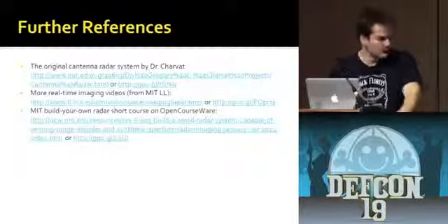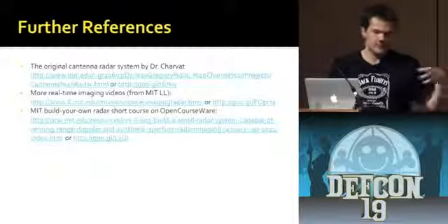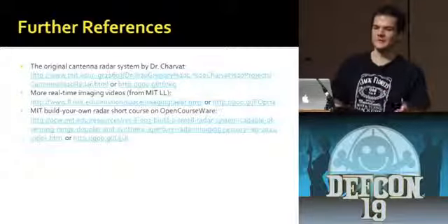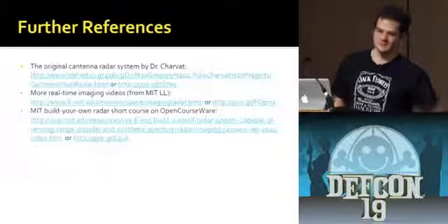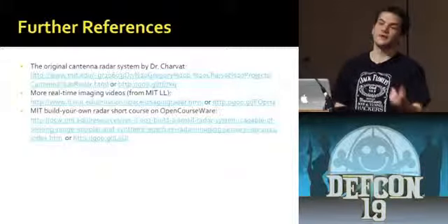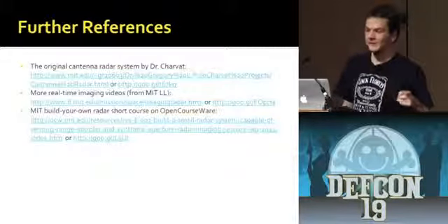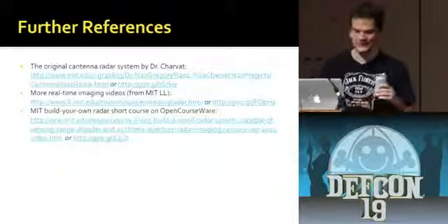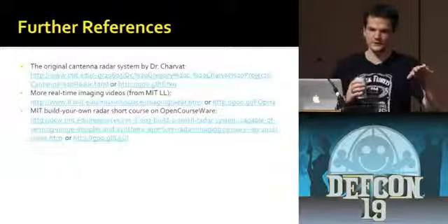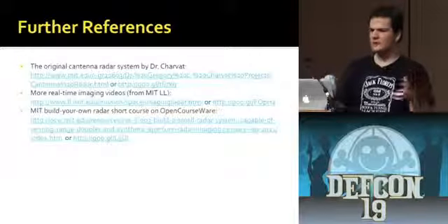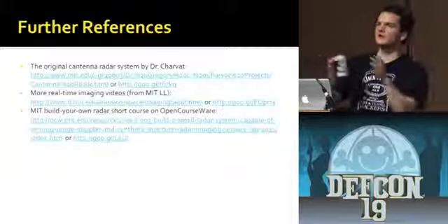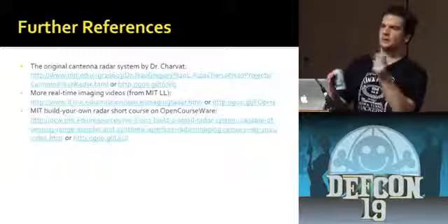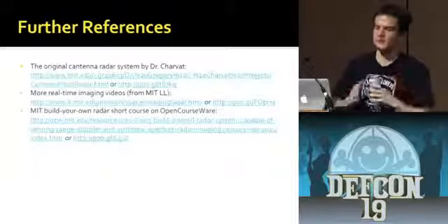Okay, yeah. To some extent, for the SAR stuff, we want something a little less directional than that. Part of it is that the coffee cans were what was available at the time, but so MIT students drink more coffee. Well, that's probably true. Yes, we could graph that. But yeah, it's pretty open. You basically get different characteristics. If you're trying to do the SAR imaging, having a wide beam width is actually somewhat useful because it decreases some of your spatial fidelity, but you also get a wider image. If you have a very narrow beam, you're not going to get any signal from something that's further apart. So it's a trade-off there.